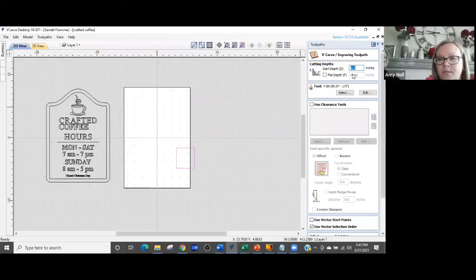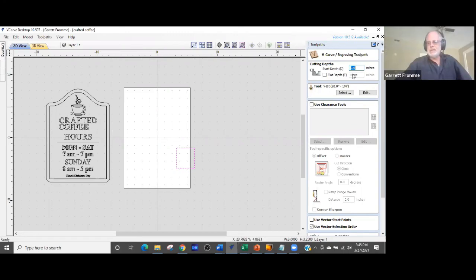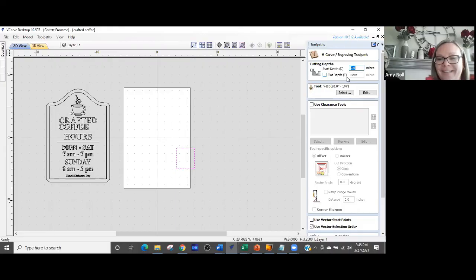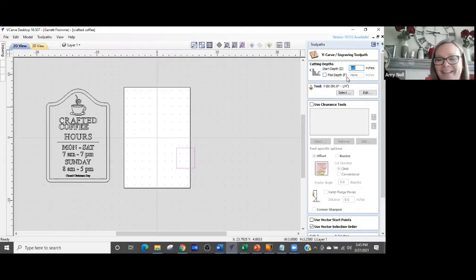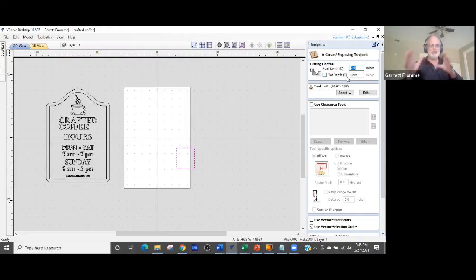Okay. So right now for my simple signs that I'm doing, it'll tell me if it's going to cut through my wood, right? Will Vectric give me an error? Vectric does have that ability. It'll calculate it out, and if any of its calculations goes deeper than the thickness that you set for your material, it's going to give you an alarm. Just so you know, if you say okay, it's going to say okay, we're going to do it, and it'll calculate it out. So you have to cancel that and make changes if you don't want to start carving your spoil board.